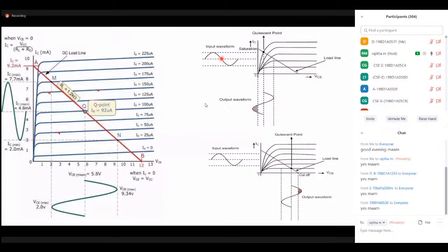Whereas in an amplifier, there is additional biasing. Biasing is the addition of DC voltages and DC currents. These additional DC voltages and DC currents can manage your transistor, which is operated in the active region. With these additional DC currents and DC voltages, your applied AC input signal is amplified at the output by a factor of beta. Your current is amplified beta times, and the voltage signal strength is also amplified.